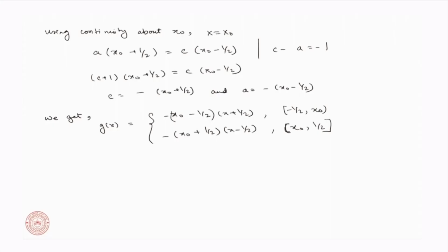Okay. Now, if you want to reconstruct this with a variable load solution, so considering a variable load, p is a function of x such that d squared u by dx squared plus p of x is equal to 0.